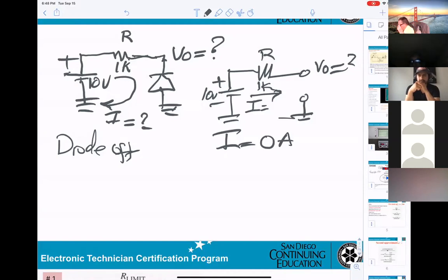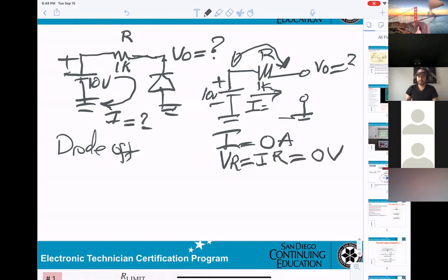Hey, Mr. Pham, up top, don't you have Vout equal 10? Not yet. For now, I know for sure I equal 0. Right? Right. Okay. Now, the voltage drop here, VR equal I times R. What does VR equal? 0. 0 volt.